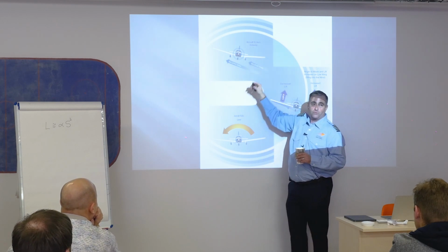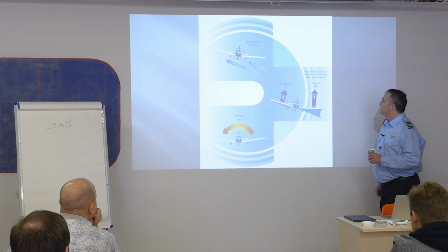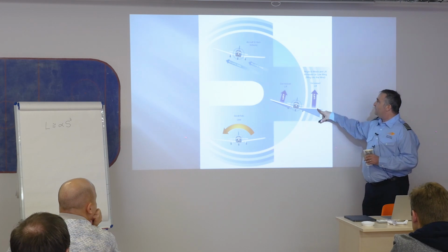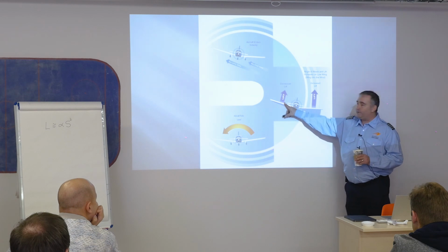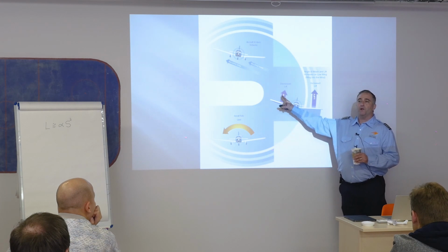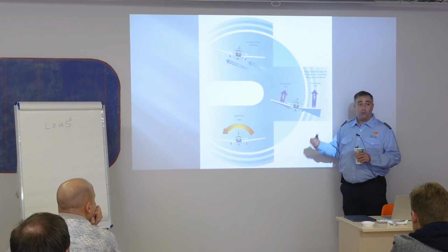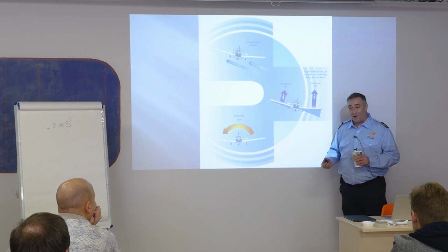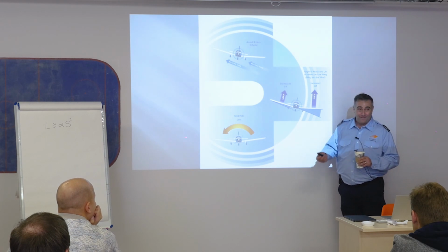You guys see the dihedral, okay? So I get increased lift on this side. It's still lift. I mean, it's a wing over here, but it'll help straighten up the airplane and roll it level. This is another function of engineers building these things so that it will fly straight without you.